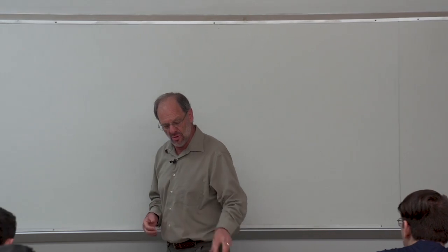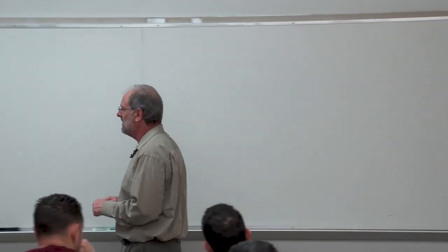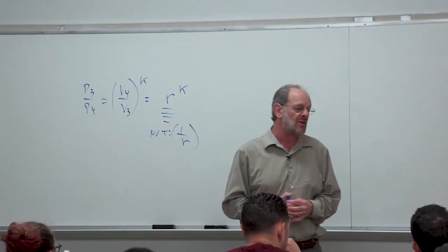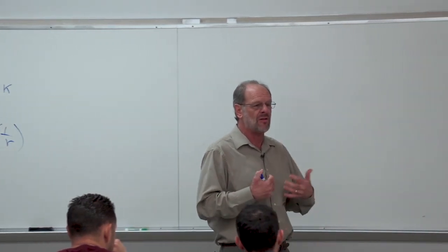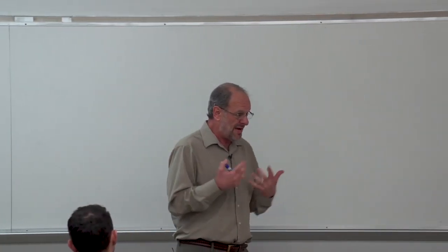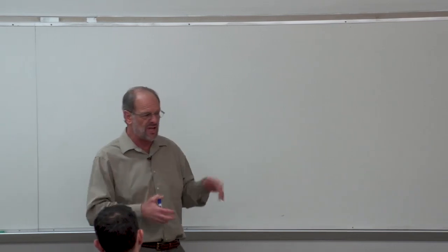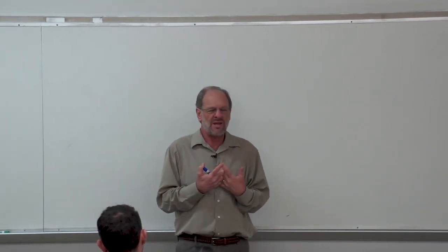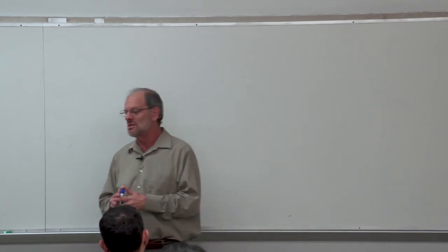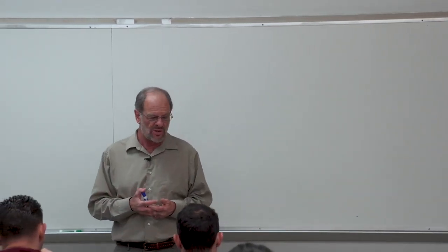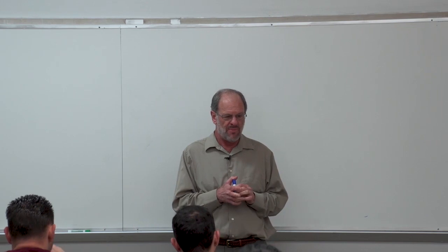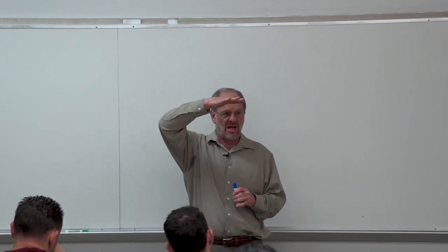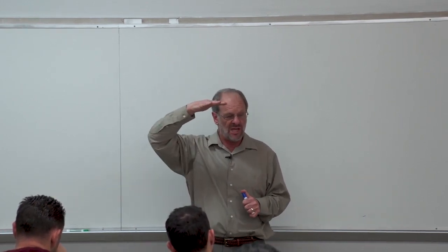One last thing I want to note with regards to the diesel engine, it turns out that the diesel cycle is honestly not even the best model for us to use for a real diesel engine. You know, maybe it was 40 years ago, but modern diesel engines are quite a bit different than traditional diesel engines. And in a modern diesel engine, when the heat input starts, the piston is going to be at about top dead center, so there will be constant volume heat input.